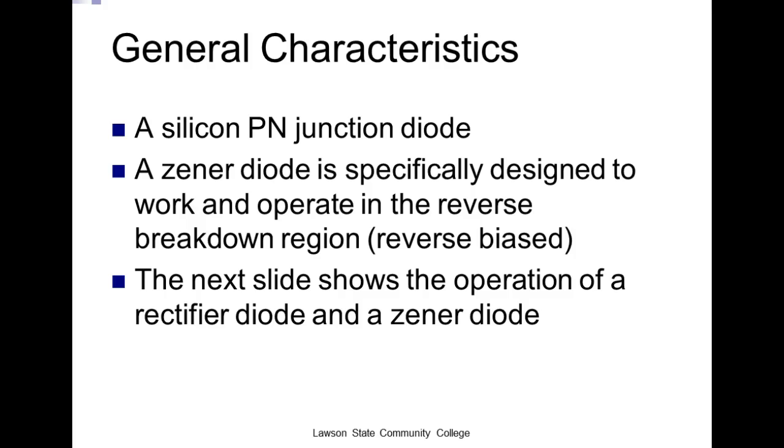So to use Zener diodes, we'll have a resistor and a Zener combination. The resistor is what we call RS, for series resistor, and it's in there to protect the Zener when it breaks over. Then we'll take the output across the Zener, so our output is hooked in parallel with the Zener. Whatever voltage it breaks over at, your load is going to see that voltage.